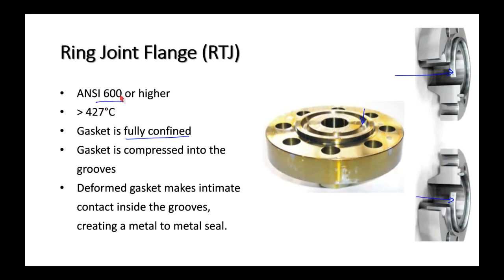So notice that these come in ANSI 600 or higher. So really, we're talking about higher pressure service, and also good for higher temperatures, over 427. It'll be the appropriate material to withstand that kind of temperature.